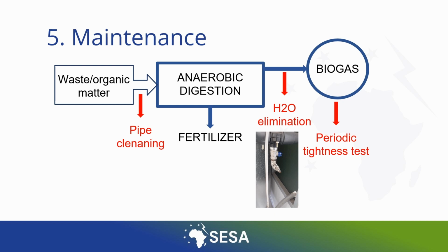As in the commissioning, it is necessary to carry out a tightness test to verify that we are not losing biogas. Again, soapy water will have to be applied throughout the pipe to check if bubbles are formed at any point. If no bubble is formed, it means that we are using all the gas that we produce in the cookstoves. In addition, this soapy water can later be used to clean the exterior of the whole installation.